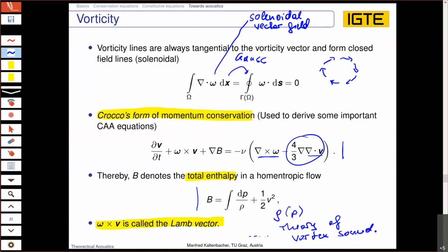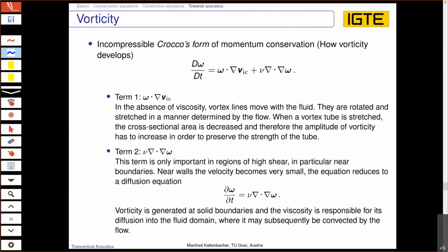And we have a very nice physical model where you really can show how out of a single vortex you generate wave propagation, and so the vorticity in this sense is a very important quantity for aeroacoustics, but as you know also clearly for classical fluid dynamics.